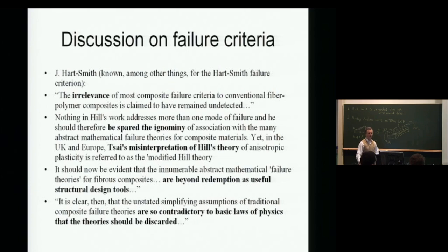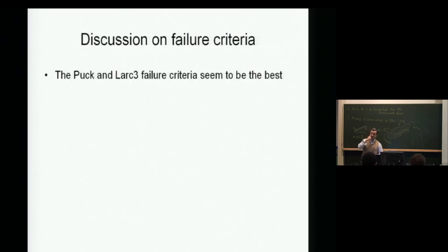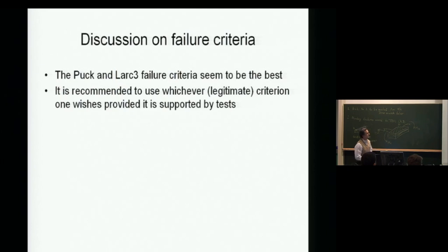That's why he came up with two failure criteria, which themselves don't work perfectly, but they are physics-based, at least make an attempt. As a message to you, the best criteria we have now that seem to work in many more cases than others are the Puck criterion and the LaRC03. The LaRC03 is much more complicated, but it's based on the Puck criterion. LaRC means Langley Research Center. 03 is the third version. There's also a LaRC04. In fact, I know the guy that developed this with some colleagues.